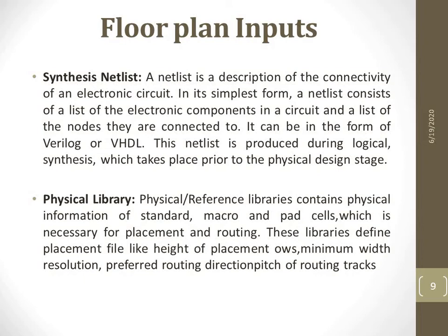Getting with me? That is due to the expression I use, or how I define it in the HDL. If I define it in some way in Verilog HDL, the synthesis tool will generate based on the design you have done in the Verilog or VHDL code. So in the second case, what I am saying is A bar B plus A B bar. When that function has to be implemented, it needs 2 AND gates, 2 inverters, 1 OR gate, 2 input nodes and 1 output node.